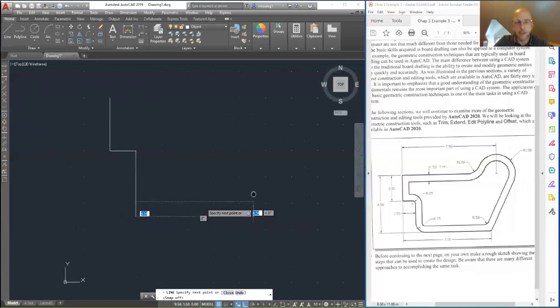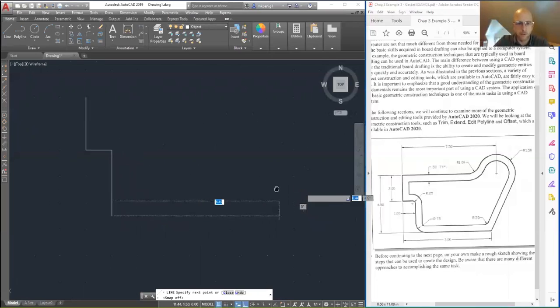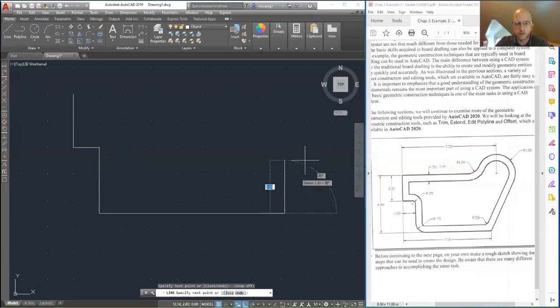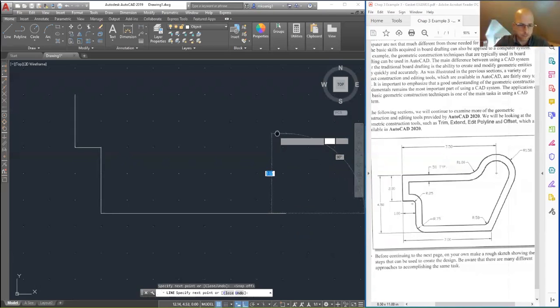Or actually, let's just make the line about 7 inches. In the drawing, you'll see a 7 inches from the origin. But let's just imagine the line about 7 inches. So without the snap, and because I don't need an exact value right now, I'm just going to click with ortho on, so I know it's horizontal. Just click anywhere when I have an approximate length line that I want. So let's click there. Right, that's an interactive selection.